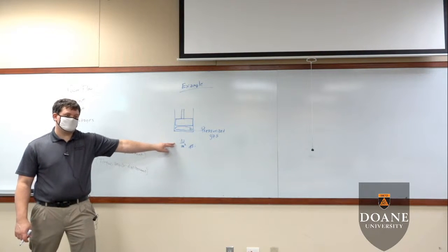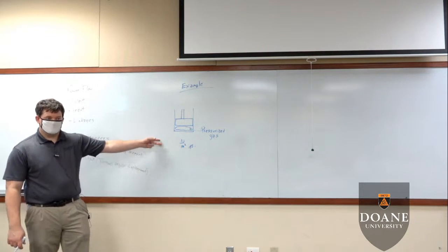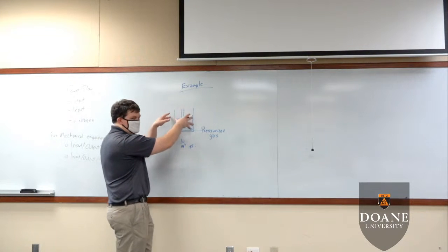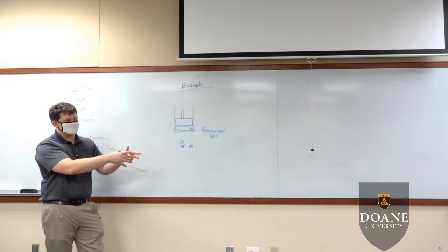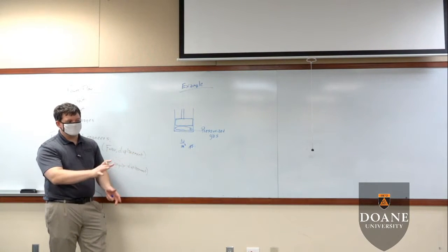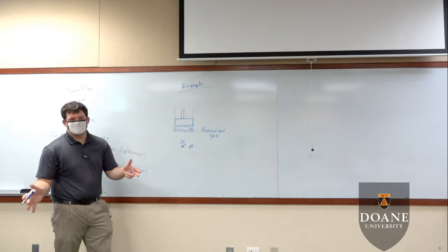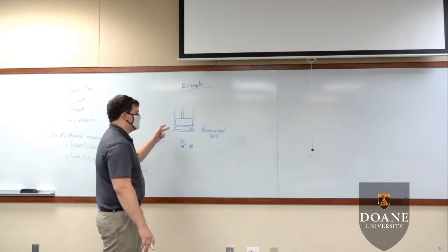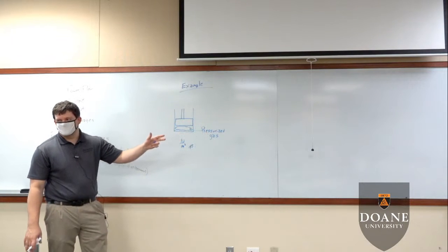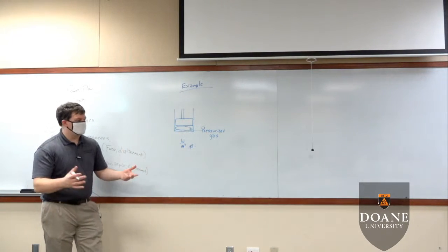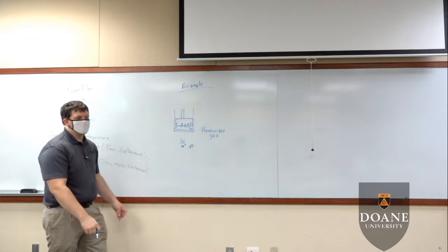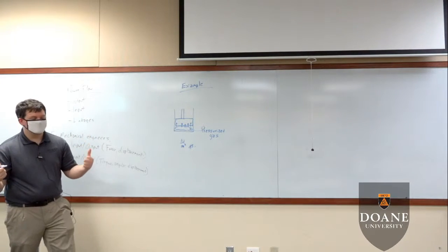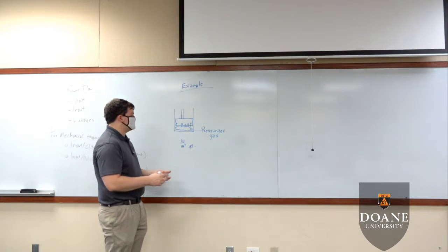If we multiply a pressure by an area, we get a force. A pressure acting over the area of the piston head, if you were to take the integral of whatever the pressure is at every location and do an area integral of it, you'll get the overall force acting on that piston head. If you calculate the average pressure in the entire cylinder, multiply it by the area, you get the amount of force, and that becomes force upward.